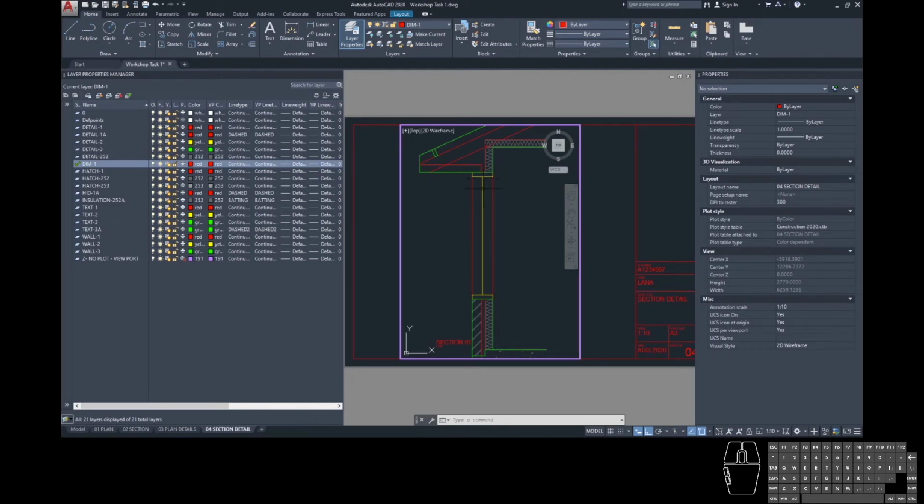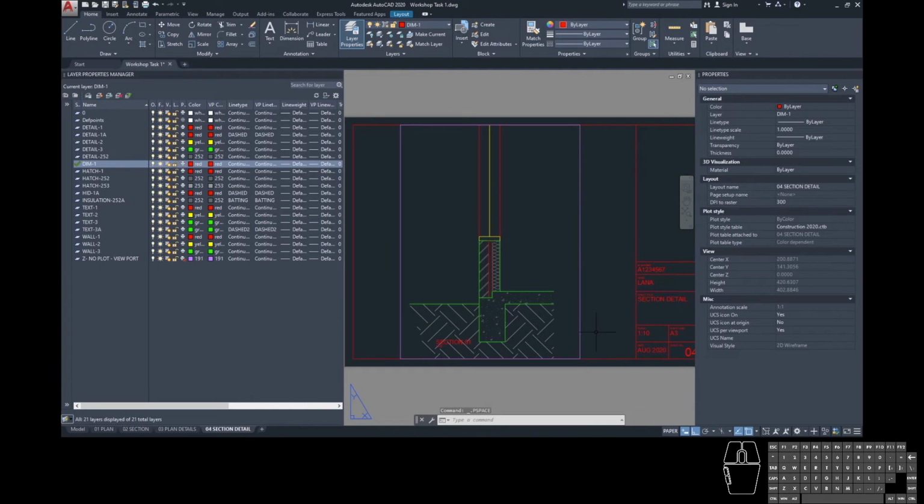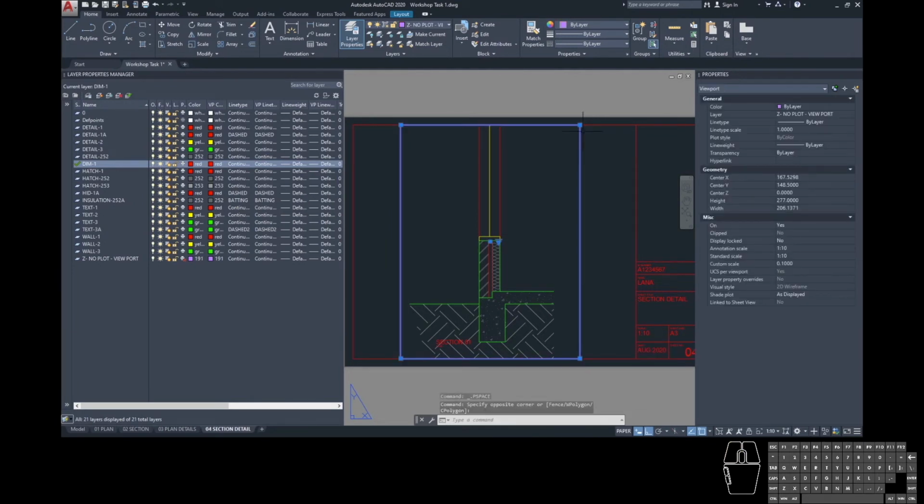So that's because at this scale, this window is really big, but it's showing the same thing, and it's a very boring piece of glass for this huge amount of space. So what we're going to do, we're going to move this up so it's sitting nice and neat there. We're going to deactivate that viewport, come back in, select that viewport, and we're going to drag that down so that we're seeing some of that glass, but not a heap of the glass.